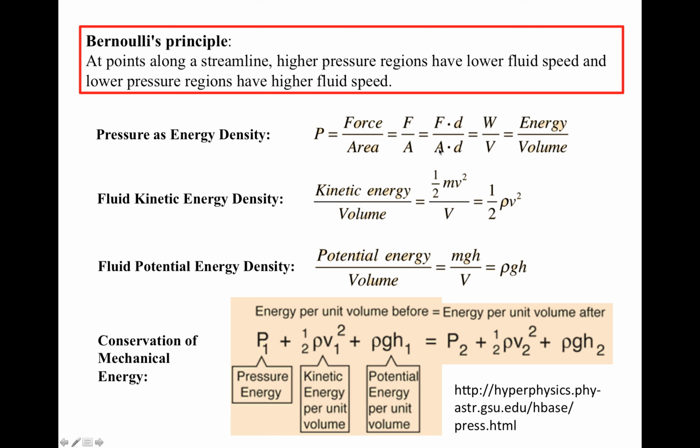And A is the area the force is acting upon, and A times d equals the changing volume of the fluid, right? Area times distance is a volume. So work has the unit of energy, and V is volume, so it's energy divided by volume. That's exactly the volume density of energy. So if you think about it, pressure actually causes some kind of energy which we call pressure energy, and the pressure itself is the volume density of that pressure energy.